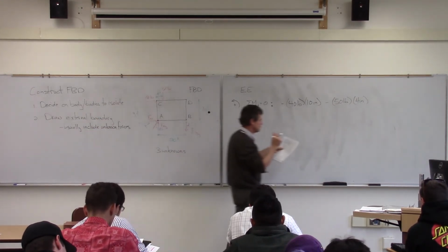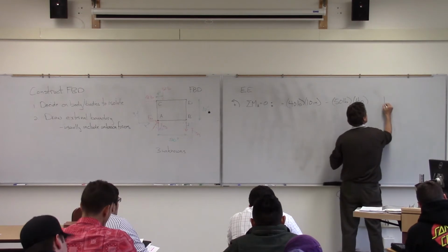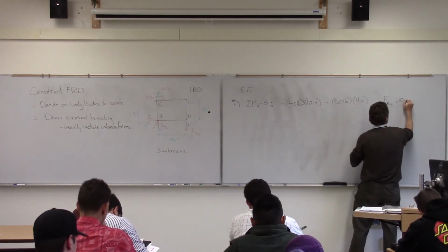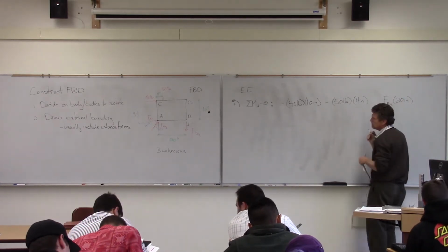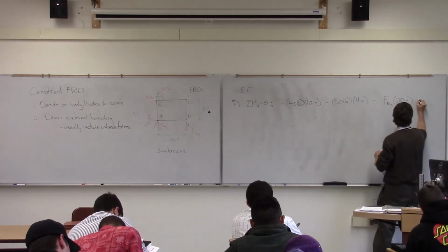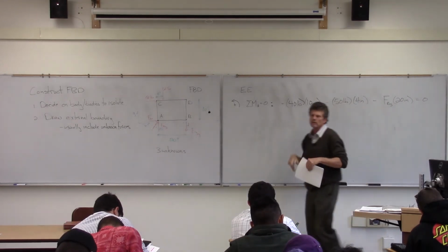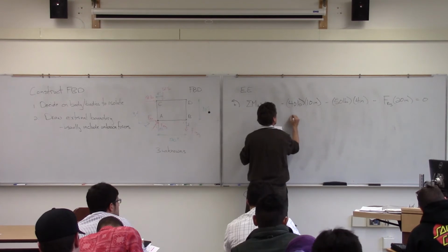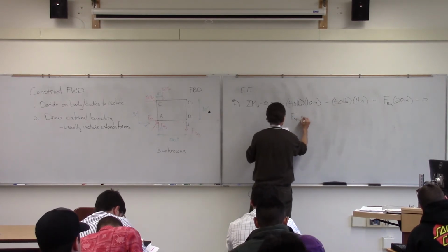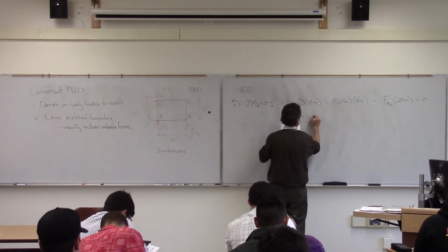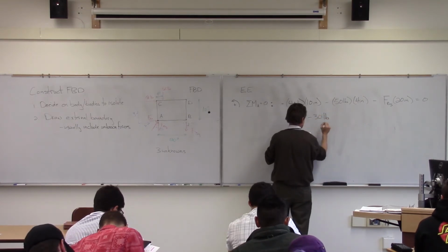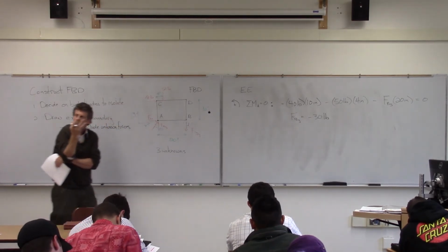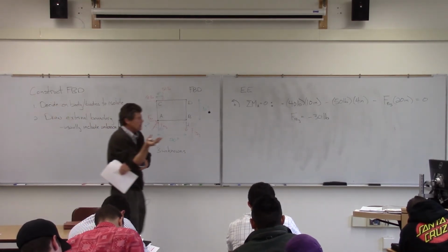Let's think about that. I put FBy now, it's an unknown, and it's 20 inches away. What's its sign? Negative. It's going to be negative also. So when we look at that, everything's negative. When I get done solving that, what I'm going to find is a negative 30 pounds. So it says my magnitude's 30. I just chose the wrong direction.